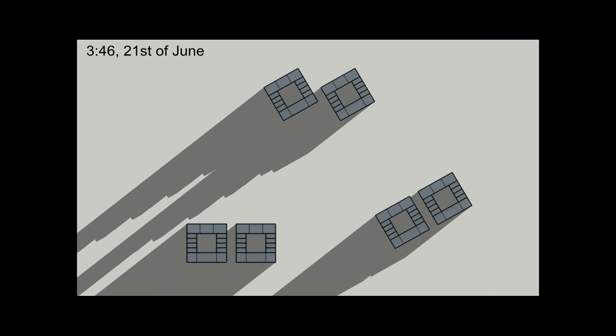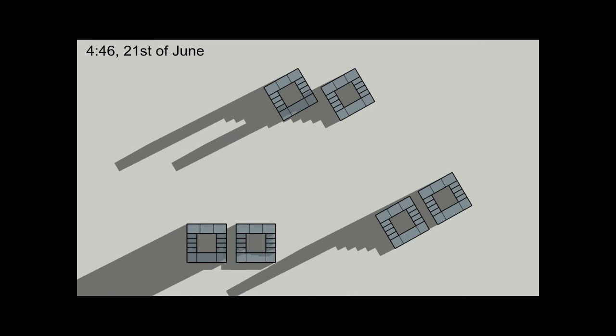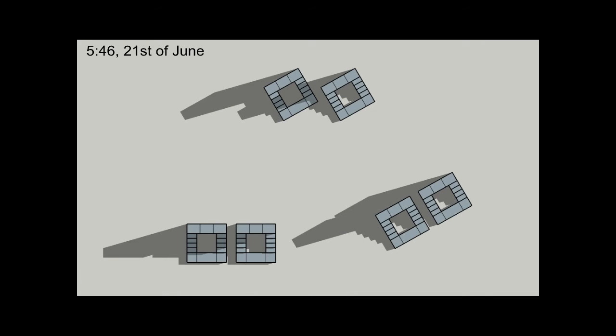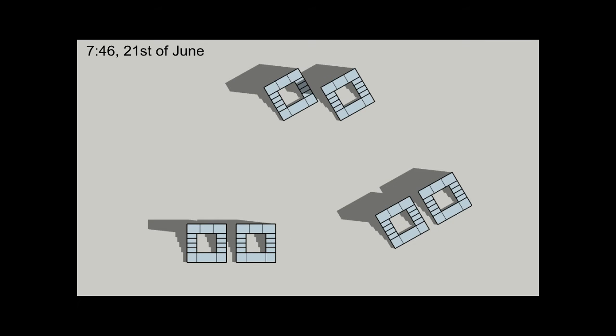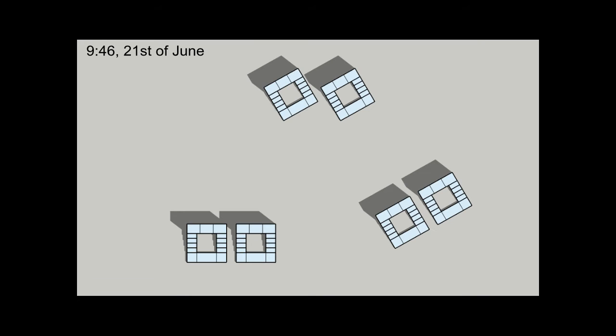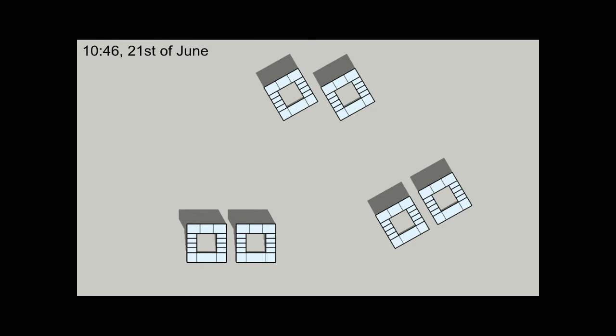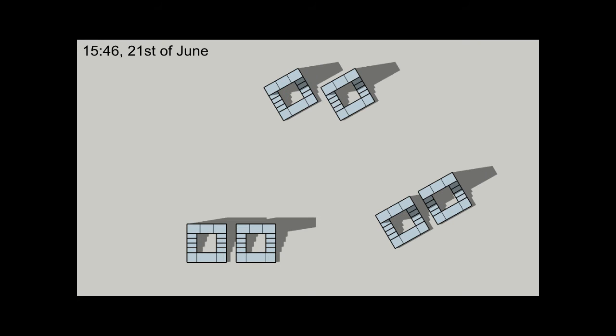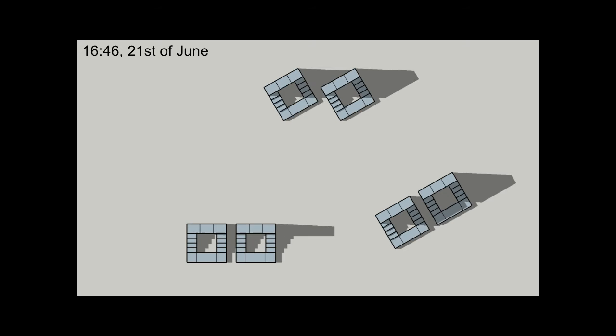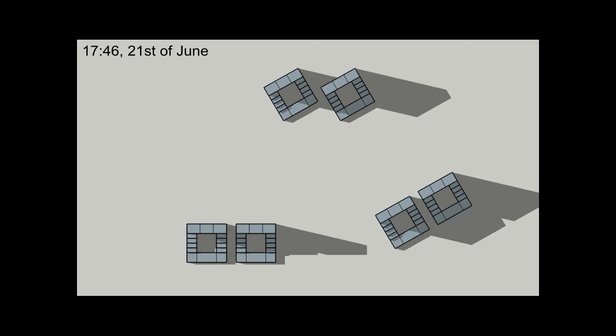The options have differing strengths. Option 1 allows the most sunlight into the streets, but it also occupies the most horizontal space. This may pose a challenge with our aim to create high-density development, that is, creating more units in less area. The relationship between blocks also feels more disjointed in Option 1 than in Option 3. Overall, Option 3 allows the most sunlight on the northern elevation face of the buildings during the evening, where most of the residential units are concentrated. And for this reason, Option 3 was chosen.